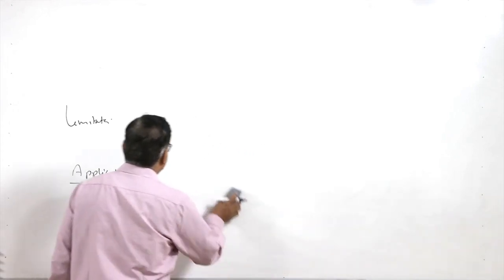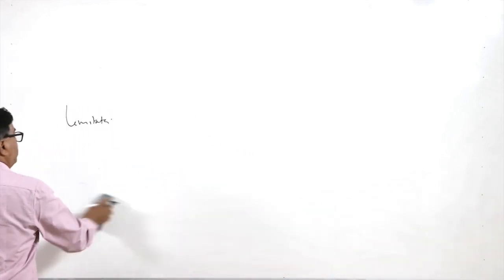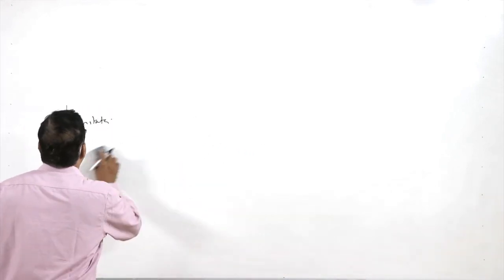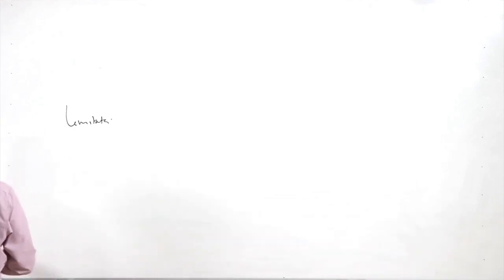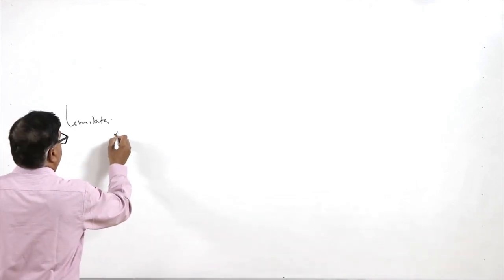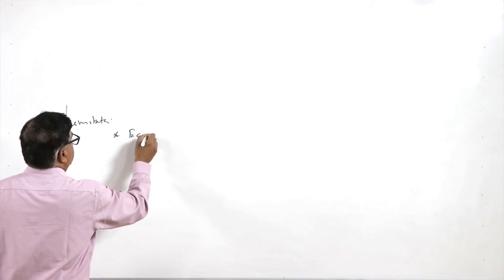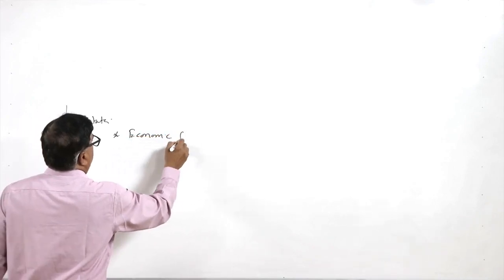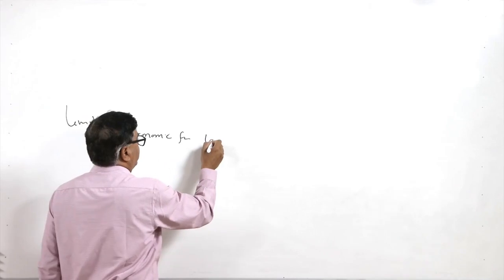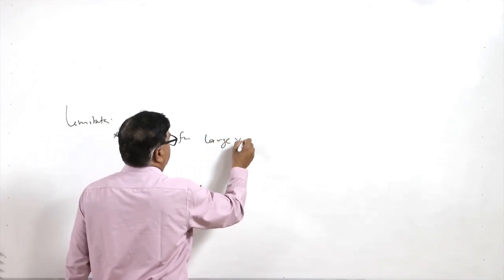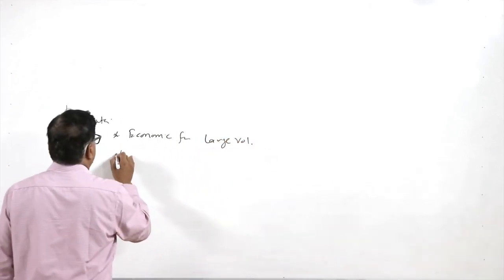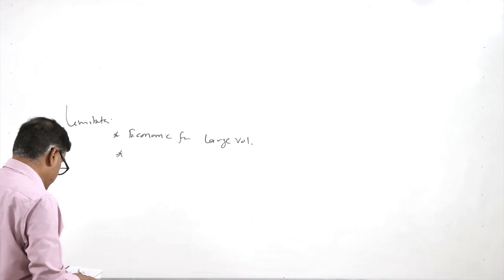That is why metallic patterns for preparing the shell will be justified only when large volumes are to be produced. So, the process is economical for large volume production.